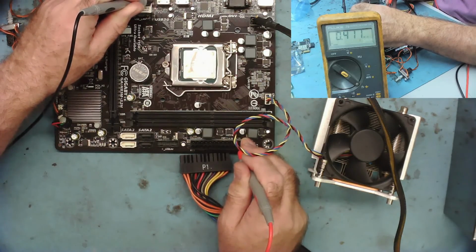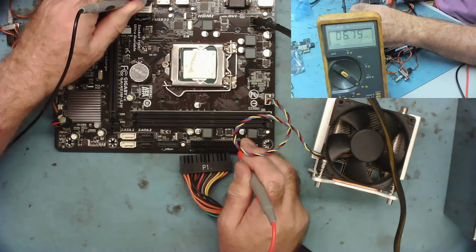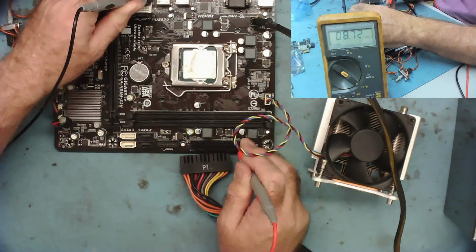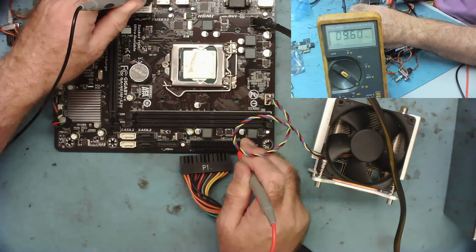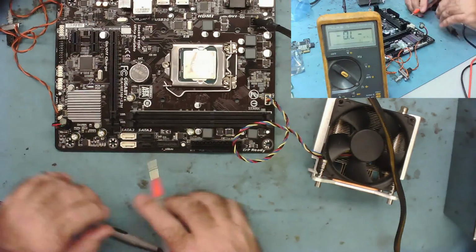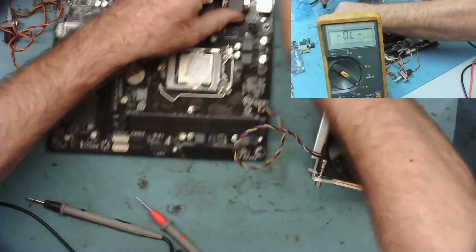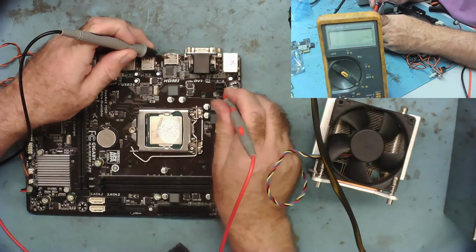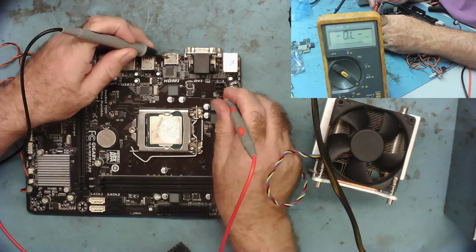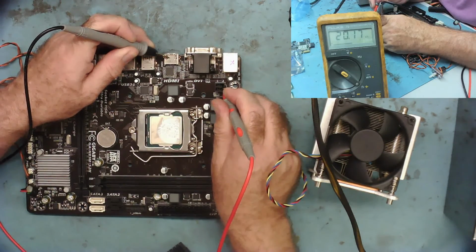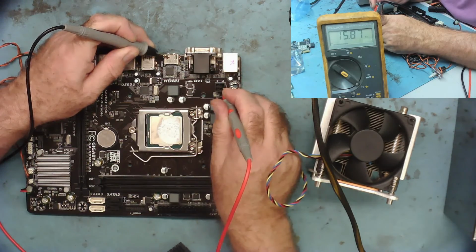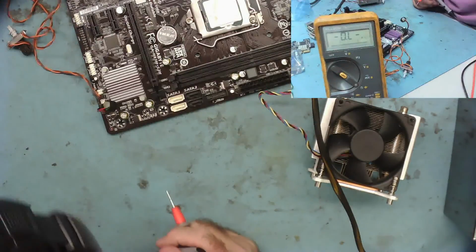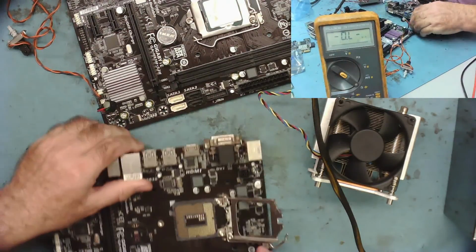It's kind of like a falling voltage. Sorry, falling resistance. But then it's going back up again. So that's like a capacitor discharging, then recharging. So that's on that one. We can also check on here, but I think it's just read high. Let's just see. Again, the rising. This is just the capacitor discharging and charging. So at least we can see what it's doing. Let's have a look at the other one. There's no shorts, that's what I was looking for, really.